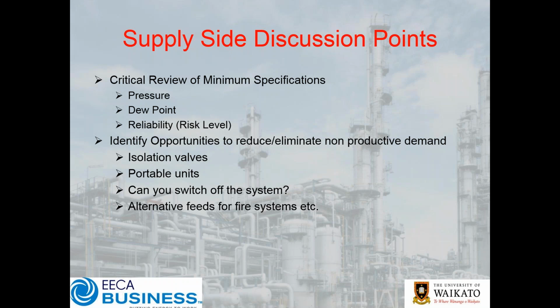Now, once you do that, your desiccant's going to be regenerated, whether it's by heat, electrical heating, steam regeneration, or it might be just purge air going through. But either way, you'll be regenerating the desiccant, and then you'll start again. Now, the reality is when you start again, your dew point is going to be that much lower, obviously, and then as the desiccant starts to pick up the moisture and become wetter, it's going to deliver a higher dew point till you get to your set point. So the reality is it's very difficult to stop that variability.